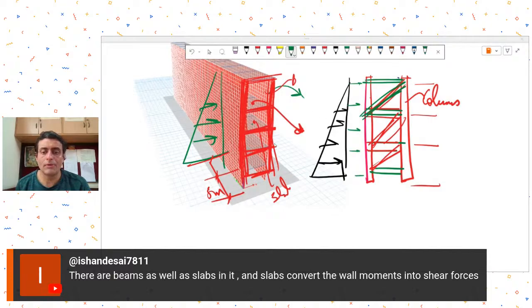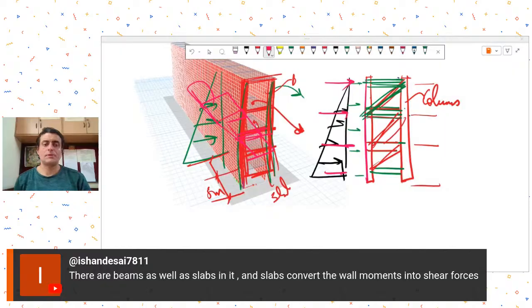And this double type of a wall is also not efficient. Instead of it, have stiff columns, have this front column, at the back have a stiff back column, and connect it with stiff beams. Imagine this to be a frame which is subjected to lateral loads. So if you were to take a building analogy, you're trying to provide thick slabs to resist lateral load. It won't help you. You have to provide stiff beams and stiff columns. Okay. Yes. So do it this way and then see what happens.